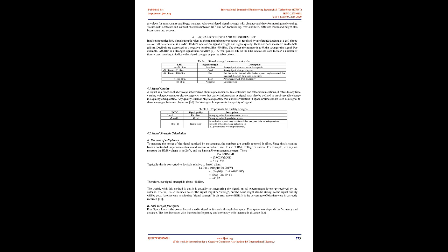In order to distinguish between the vertical and horizontal components of the incoming signal, the measurements are performed for horizontally and vertically positioned mobile terminal. In winter, the receiver receives better signals because tree leaves fall off in the surrounding signal area. Tree leaves contain a lot of water and cause moisture, and thus they might block radio waves. In rain, better or worse signal can be received, because it washes away pollutants in the air. On the other hand, the worst signal is received due to humidity, as most of the signal gets absorbed by water.